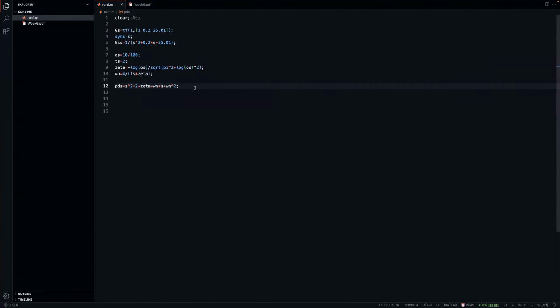So this is the polynomial way of saying that. It's basically the same. But now, since we're going to design a PID controller, since we know that this is a second order transfer function, we know that the closed loop will be a third order transfer function, which means that we are going to introduce a residue pole, and the residue polynomial is going to be s plus p. So up to this point, we've basically come up with the ideal closed loop characteristic polynomial in our mind.